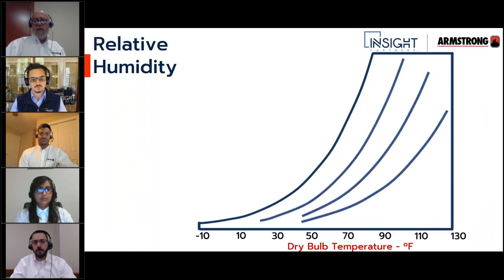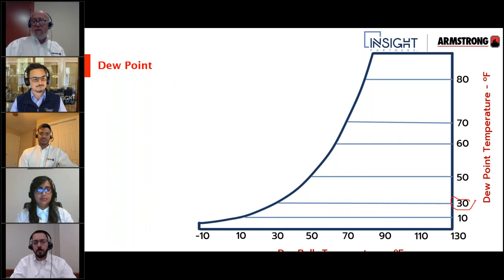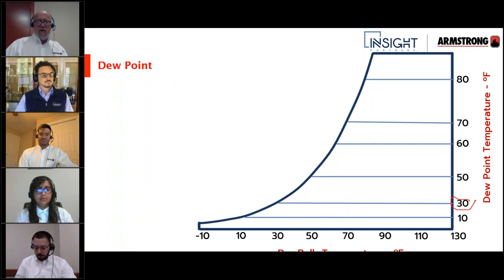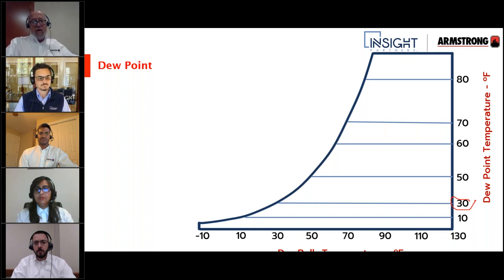Tony, we had a question come in from somebody asking about equalization with adjacent spaces with possibly different humidity levels. Understand that one of the things that will happen with humidity is humidity will always try to go into equilibrium across a building. It will always try to get to the same value everywhere. This is the reason we have vapor barriers in buildings. We have a vapor barrier on the outside wall. You've got your exterior construction, you've got insulation, then you've got a vapor barrier between the insulation and the interior surface.